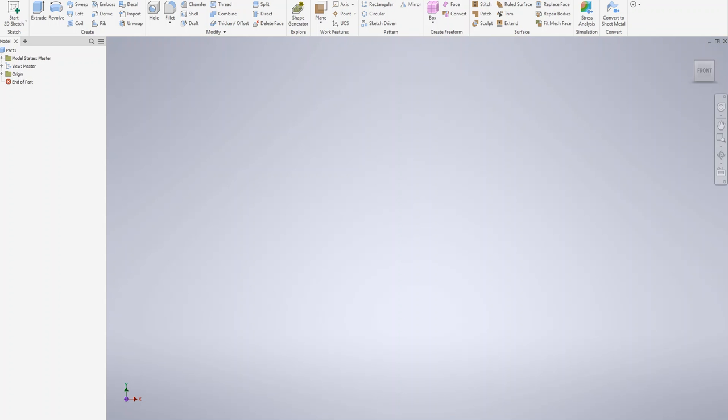When we create the one pedestal drawing, we're going to save it under the name pedestal, and then move on to the first piece, the pawn, and save the same pedestal drawing under the name pawn. If you start the knight 3D model, you start the pedestal drawing and then save it as a knight. This is how we're going to do it, to save time and energy and money, perhaps, every single time. So the pedestal has to be created and saved under the name pedestal first.